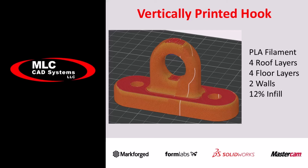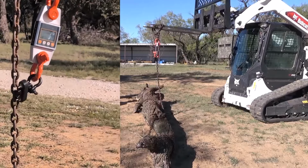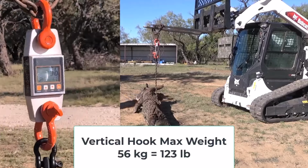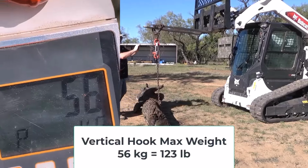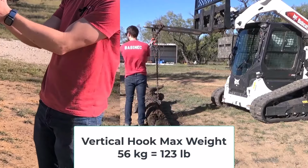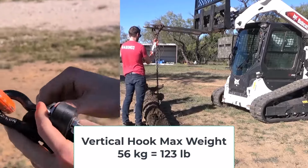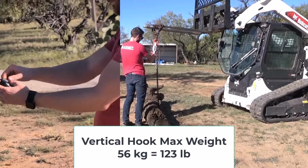Experiment number 1 is our vertically printed hook made out of PLA with 4 roof and floor layers, 2 walls, and 12% infill. There we go, starting 20, 30, 40, 56 is where it broke. 56 kilograms, all right. That's a benchmark. And it snapped right where we thought it would, right along the hook there, where it's really thin. Not too much grabbing on. Yep. So let's see how it compares.